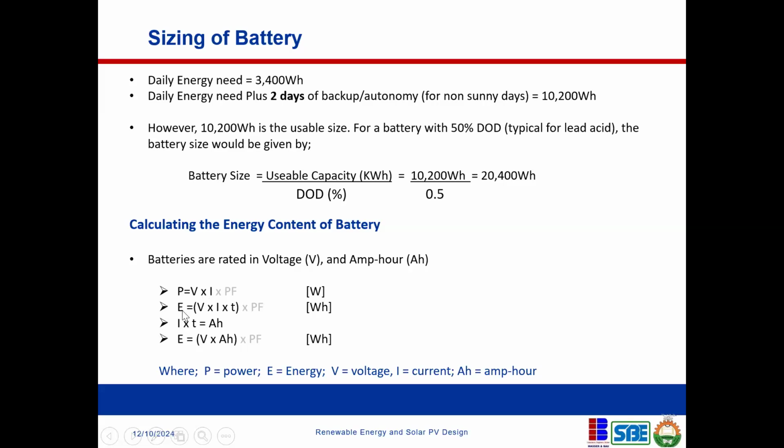If we make so energy, what we're actually driving at is the energy content of the battery. So energy is equal to power times time. That is, power is equal to voltage times amperage, and then times time, which is energy. If you do that, you have your watt hour. Okay, that's what we have, watt hour.